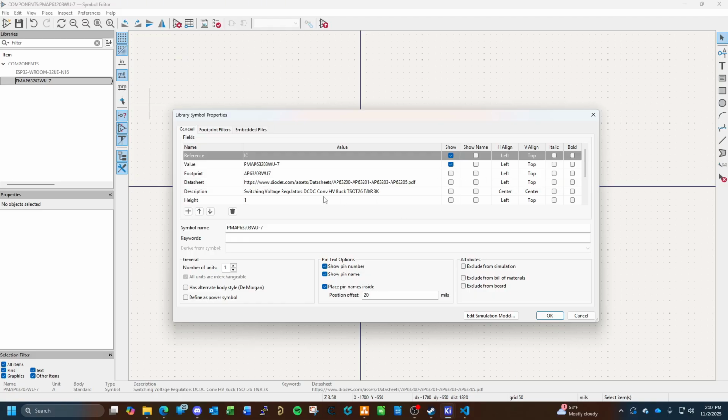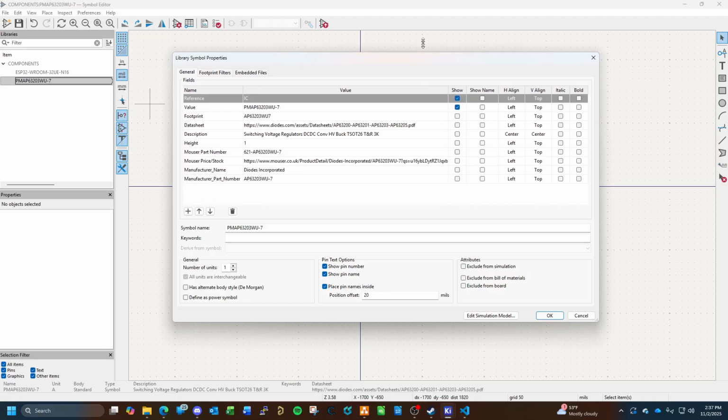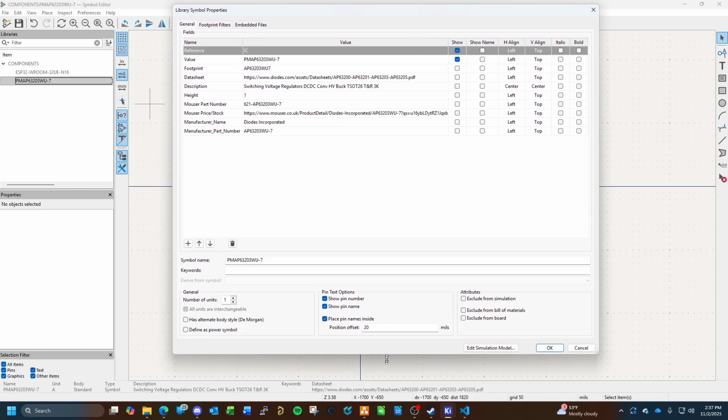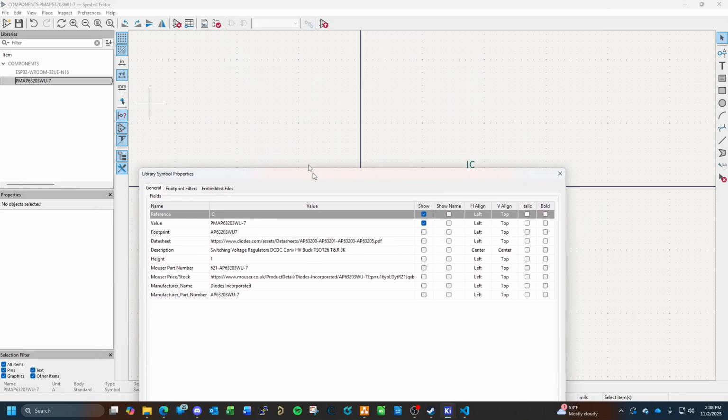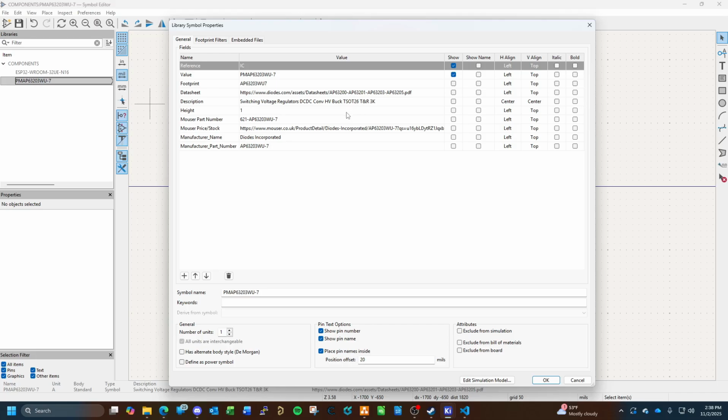If this works similarly to Altium, we're going to want to clean this up and stay consistent. Can I make this window bigger? Yes, because that's another powerful tool we're going to use. So it looks like these are okay fields, and chances are these actually get translated over to the bill of materials.